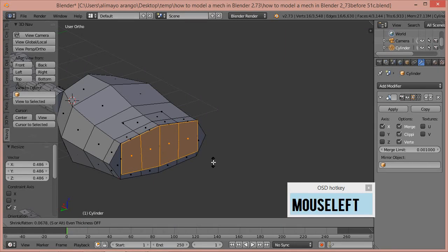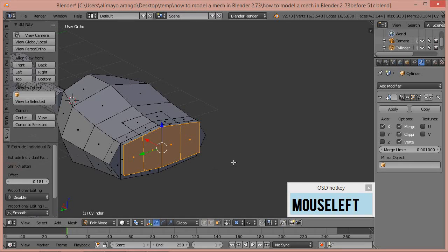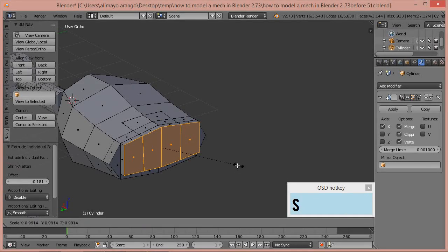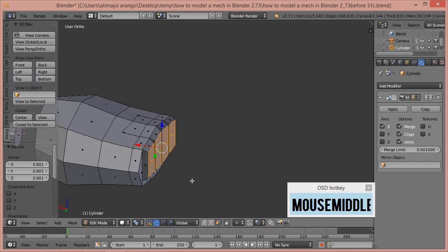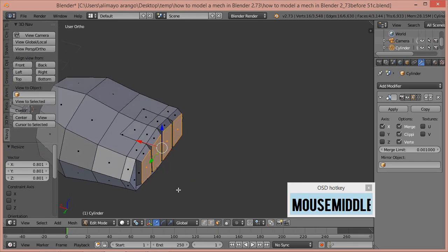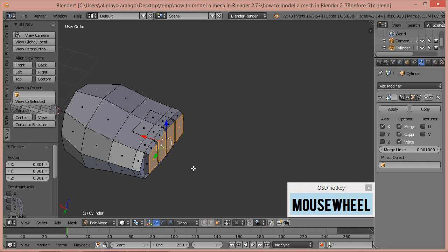We're going to pull out just a little bit, left click to lock in, press S, oops, we need to turn this off. We're going to click here, click disable, and press S to scale. Because we set up the individual faces and this pivot point, when we scale this now it separates. Normally, if we didn't change it to individual origins and extrude individual faces, when we had these all selected and scaled down, it would all scale as one. But because we put on individual origins and scaled it down, it separated like this, which is a nice setup for fingers.